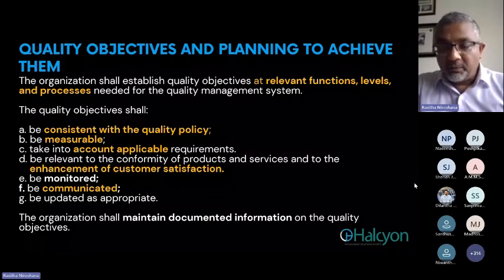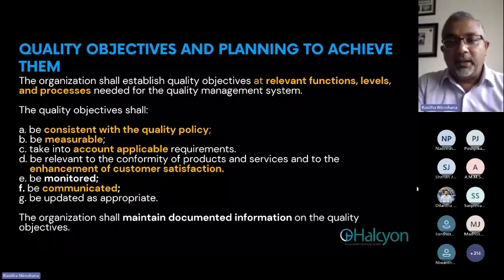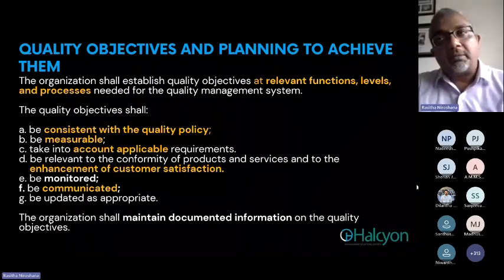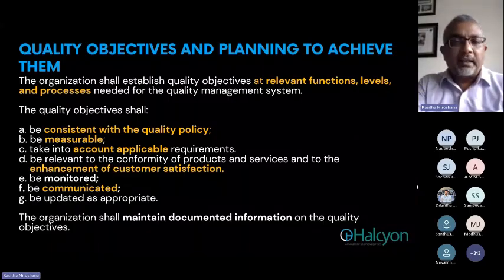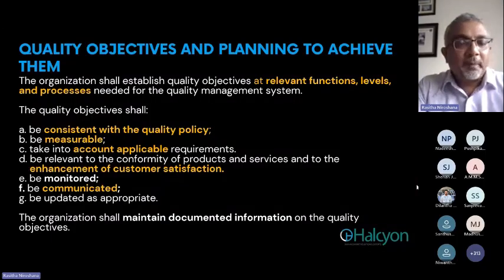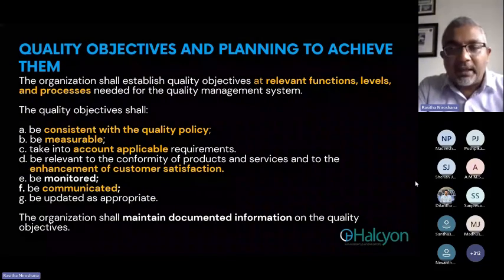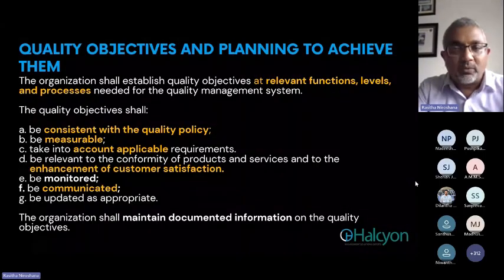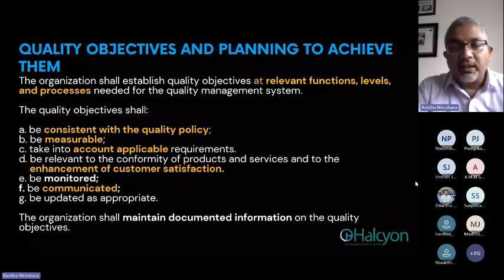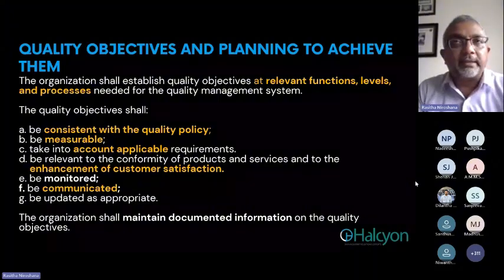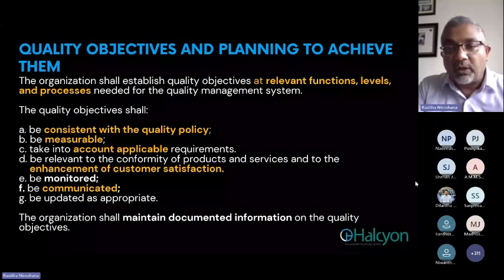Water usage per batch, superb. Nowadays we talk about the water footprint. In the food industry, we use a massive amount of water, right? Sometimes, even in the washing process, the CIP process, cleaning in place, we use a huge amount of water. So if we can cut that down, that is waste reduction. A water audit has now become kind of a requirement for the industry. Especially in the food industry, if you're using reusable bottles, especially glass bottle packing lines, the amount of water that goes into the washing process is a lot.